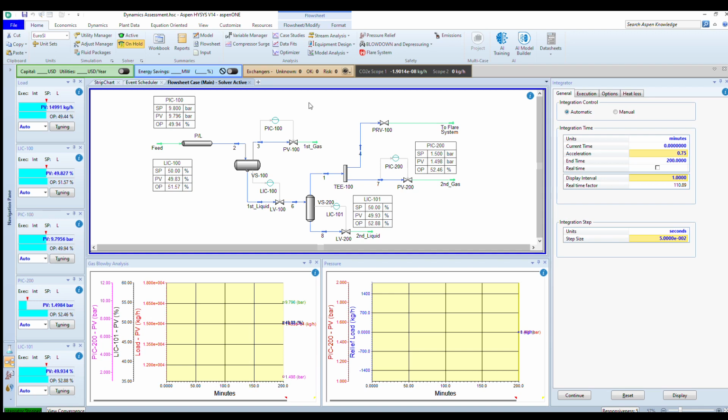Someone would argue, I don't need to rely on any existing IPL in the system. So this pressure control system and level control system on the LP interface should not be taken as a credit. And I need to assume there is no means of protection except the ultimate protection, which is the proposed PRV.